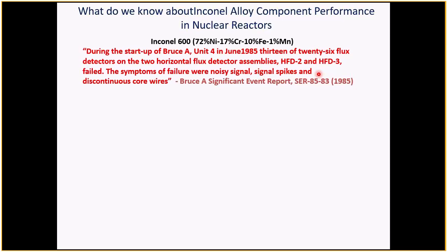Some other people thought it was nitric acid attack, because Inconel 600 is susceptible to nitric acid attack, and you can get nitric acid formed in areas where you have a high gamma field, because of the ionizations of the air.